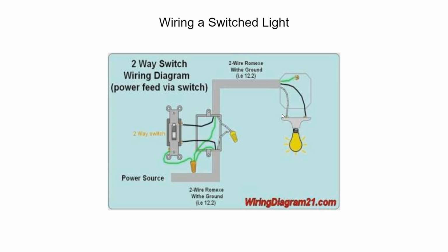Think silver looks white, so white wire goes to silver. Green wires or ground wires go to green screws. So we have also copper. So copper or ground. So think green ground, go to green screws. They're painted. Black to brass. Silver is like white, so white goes to it.